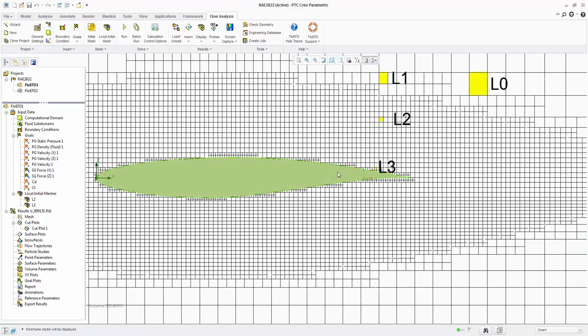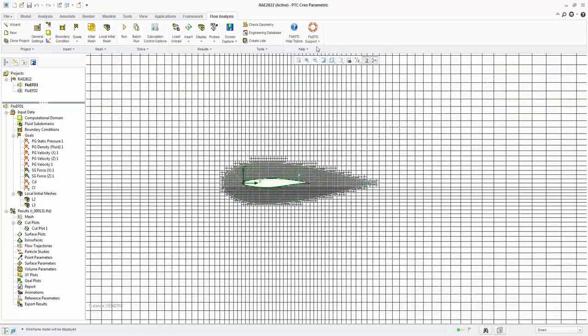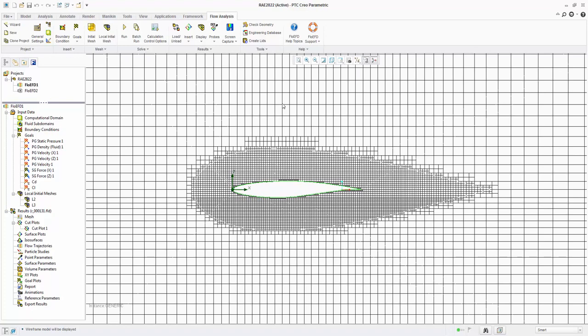The mesh system in FloEFD works using levels. The base mesh is referred to as level 0. Octree meshing technology means that a single cell is then split into 8 cells to go to the next level up. We can see level 2 grid cells in the mesh region and level 3 at the walls. At this stage, no solution adaptive meshing has occurred.